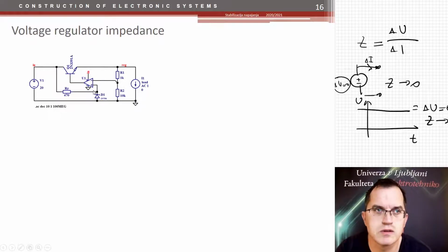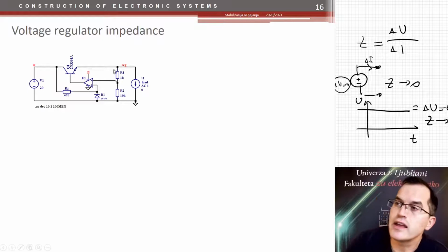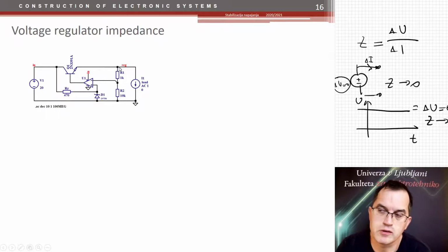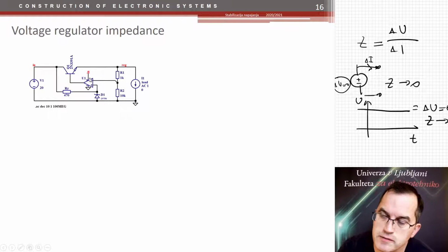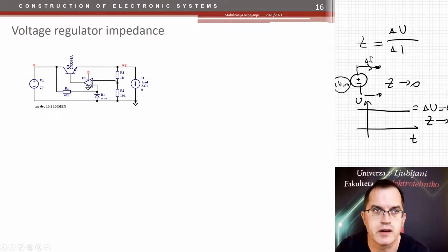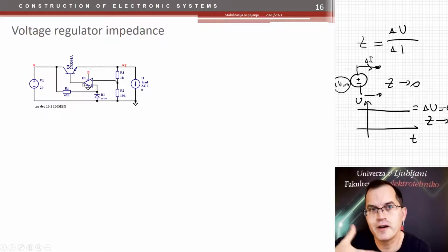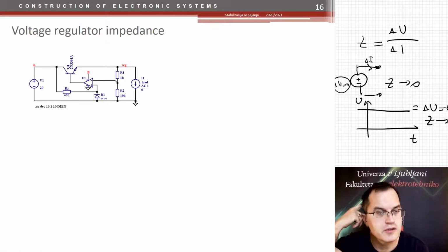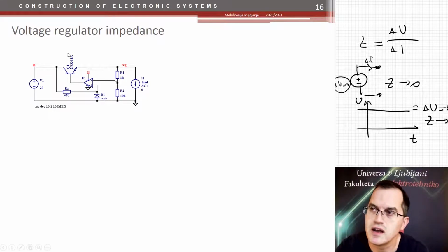This is a reference voltage. Then you have some sort of a transistor that defines the output voltage. It's a regulating element. And then you have a feedback consisting of some resistors and a feedback amplifier. It's an error amplifier, and this error amplifier is not the fastest there is. So what that means is that if DC current, or low frequency current, is taken from the power supply, the regulator can follow the changes in this current and can control this transistor in real time.